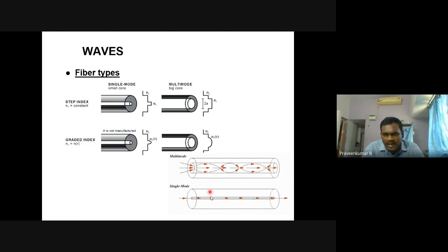To understand the purpose, for the single mode fiber, this is single mode transmission. For a multi-mode system, this is multi-mode transmission. This particular fiber diagram gives the parameter of a multi-mode graded index fiber. You can see here the signal is not traveling in a normal sawtooth wave structure. You can see the sine wave structure. Whenever the signal is transmitted in a sine wave structure, you can understand that the core value n1 varies with respect to the radial distance r of your system.